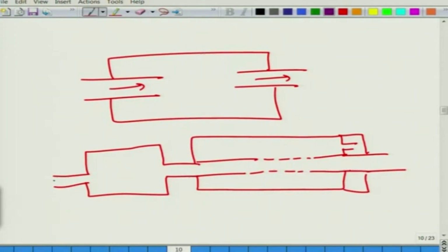So, with the understanding that there is a uniform unidirectional propagation of acoustic power, under such a situation, what we really get is that the transfer matrices can be cascaded. That is to say, let us say this is the transfer matrix for this element is 1, this is element 2, because now this length becomes important, although it is uniform, because it is connecting two different muffler elements.